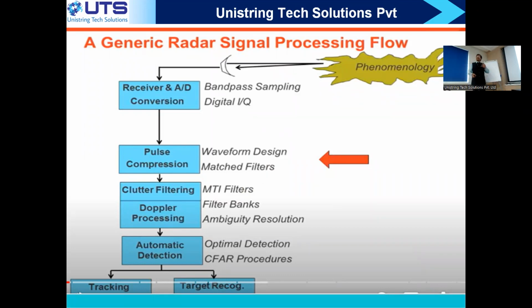Okay. So when you say, sir, it's okay, clutter I don't want, 1 meter per second is also not required, 2 meters also, 5 meter also is not required. Can you give with the low false alarm? Yes, it is possible. Because wherever the clutter leakage is, that zone you are letting go. But let's say I'm interested in 1 meter per second also. Obviously, you have to live with increased false alarm for the same environmental conditions.